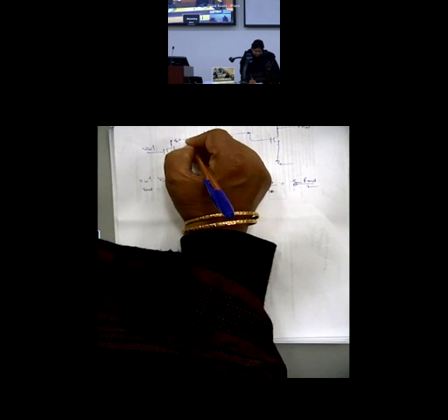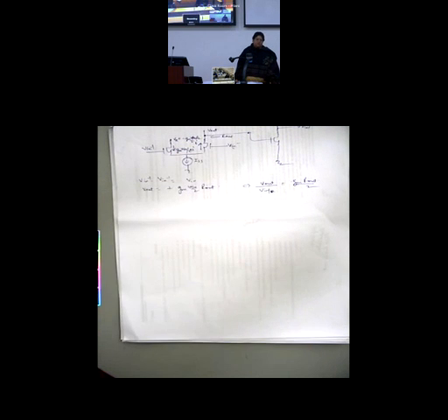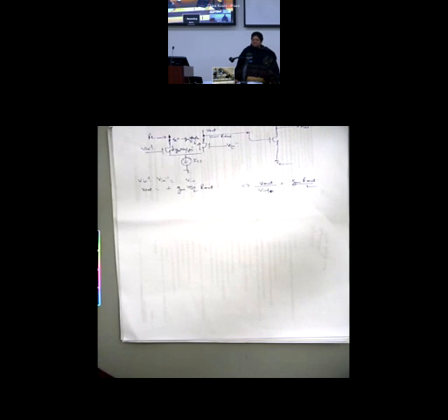So I have to reflect the mechanism. What will be this output? Let me call this my intermediate node Vx. The potential here is going to be minus GM Vin by 2 into Rout, whatever is the resistance at this node. So there is AC current dropping across the net Rout. AC current is generated by the amplifier, the differential pair.